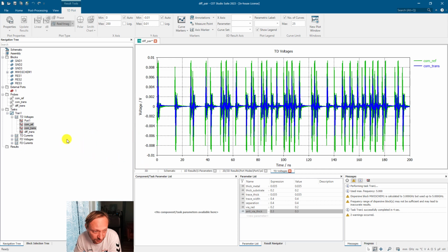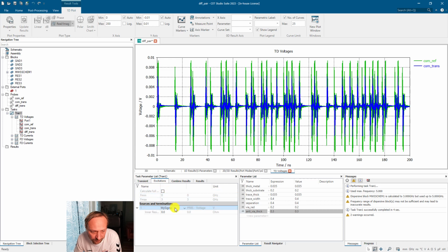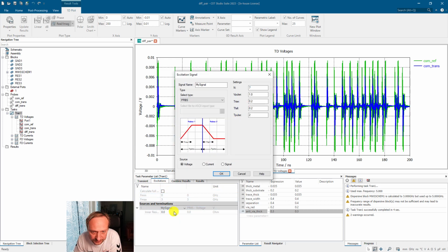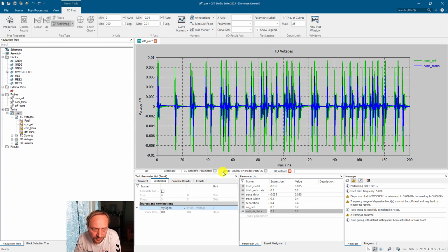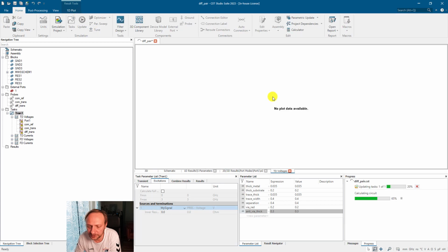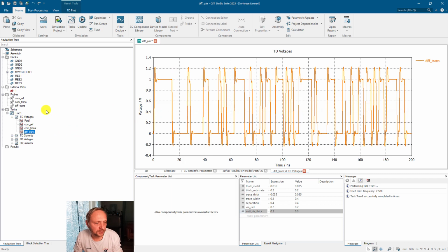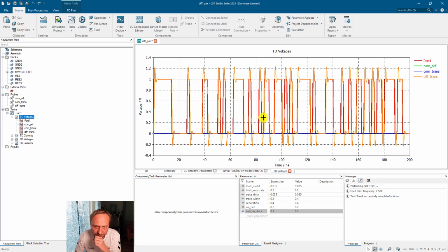My signal was a little bit too fast that I have used here, because my 3D simulation didn't do broadband enough. So let's make the rise time a little bit less. We should get no warnings now, exactly. And probably also our signals should look a little bit better, not that much. So okay, we got this.